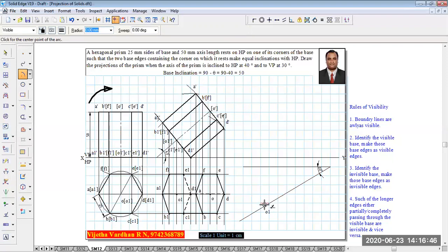Next, keep the compass at O1, and without changing that radius, draw a constructional arc over here like this. Once this constructional arc is completed, draw the locus line over here. The moment we complete the locus, this point is going to be called the O of true length.